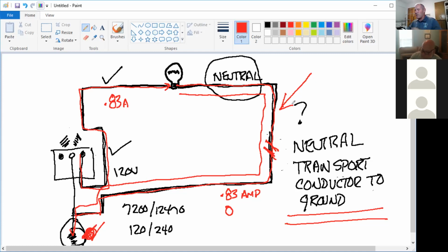A lot of this is going to factor into the future of how you work on conductors, both an energized conductor and the neutral. When a bird lands on a wire that has 7,200 volts on it, why doesn't it get burned up? Why doesn't the bird die? Because it's not grounded. It doesn't have a complete path. There's no path. It's just sitting there.